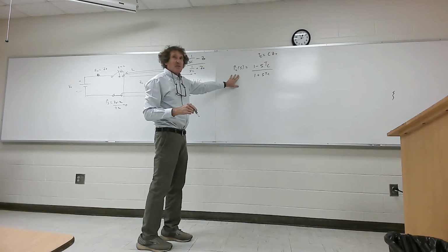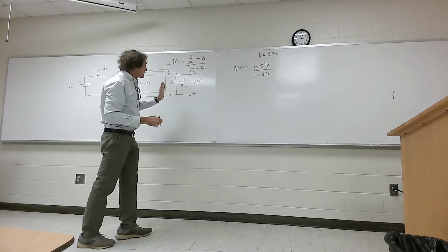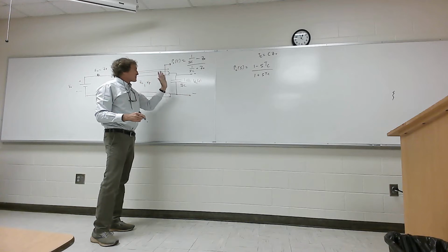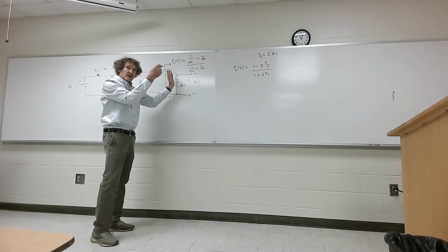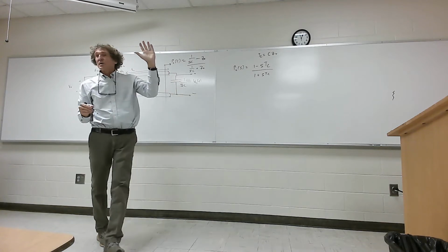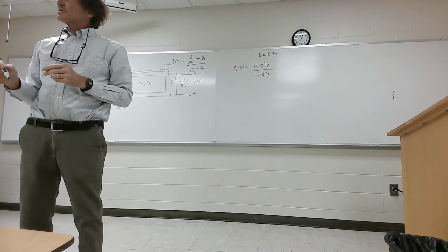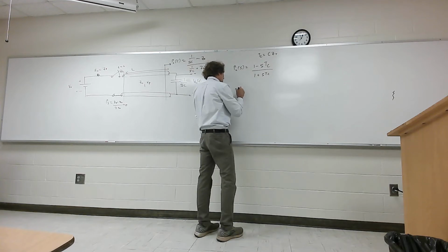All right, now, when you take a look at this, what I want to do is figure out the voltage here. Now, do you all remember in those bounce diagram models that really the voltage here at the load is a superposition of the incoming pulse and the outgoing, or it's 1 plus gamma? That's actually the transmission coefficient. Do you all remember that? 1 plus gamma is the transmission coefficient. So that's what I'm actually after.